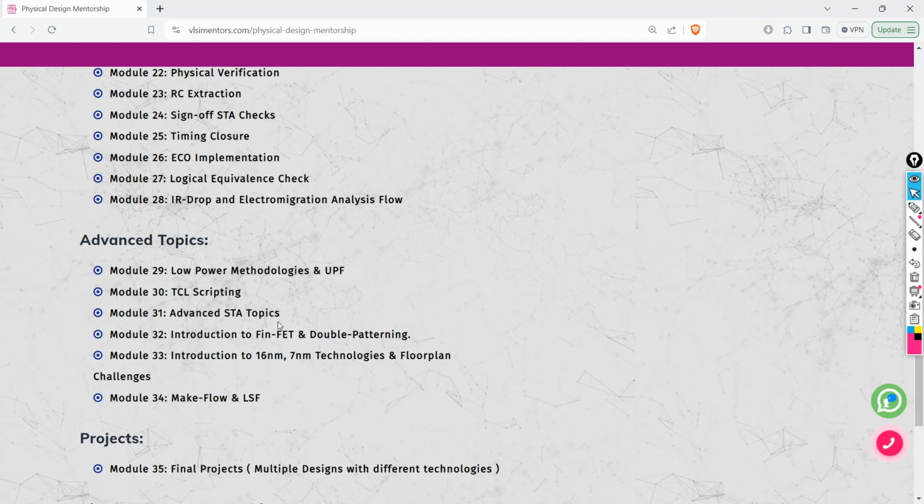Now how do you go about looking at the path placement? Now you want to look at what kind of violation it is, what kind of cells, is it in a congested area. To that level, looking at your DB, and then coming up with the fixes, and then you also get a chance to learn setup aware hold fix and everything.